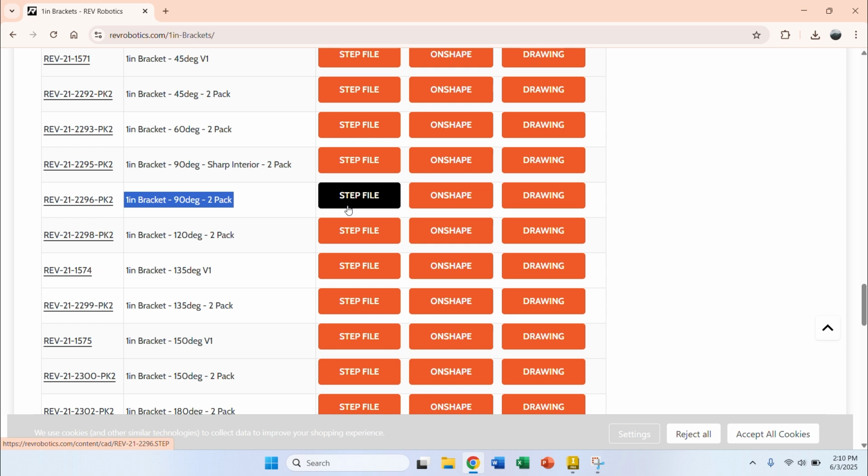This brings us to our first topic: files and different file types. There's a million different types of files: OBJ, STL, vector, whatever else. The most important one that you'll use for CNCing is a STEP file. That is the file type you're going to use. Everything else, like STL, is not great, a hassle, and miserable to use. So if you're downloading a part from Onshape, like the robot CAD, to CNC, you want to download it as a STEP.